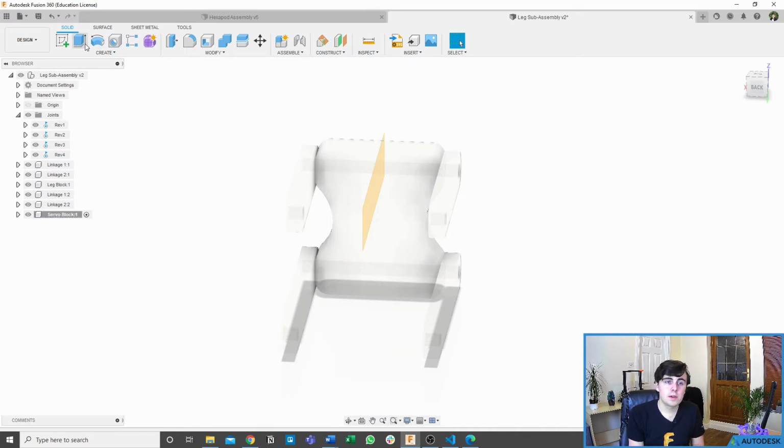From here, we can go in and create a sketch on that part. And you'll also notice that once you've created one of these planes, a construction folder will appear in your component. This is plane 1, and you can rename them if you really want to. You end up with a lot of planes, and you can rename them to make sure you know which one's which.